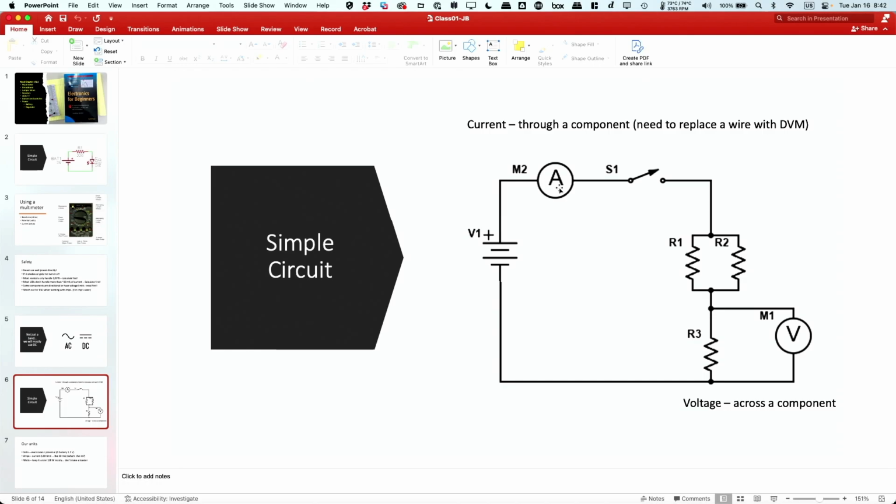That's not really the way an ammeter works, but it does have that same property, that the current needs to flow through it for it to measure it. So you need to break a wire, stick your ammeter in, make the measurement. To take the measurement of the current, you basically interrupt the circuit so that all the current goes through your measurement device.